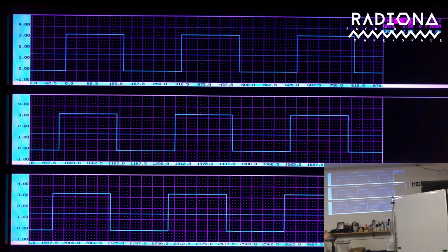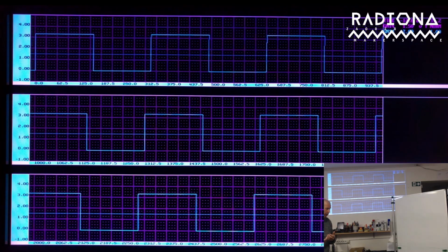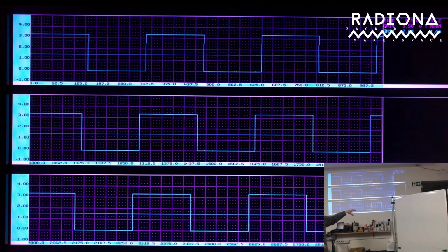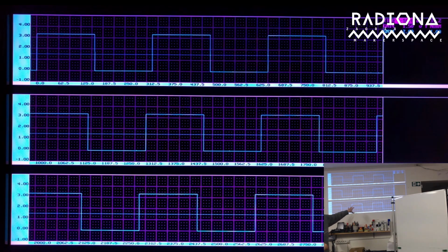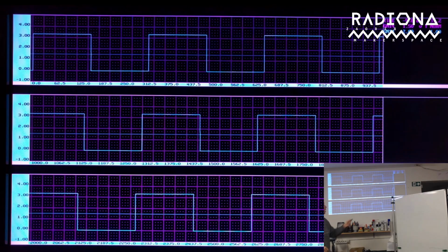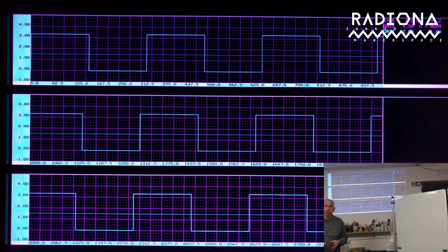So what you are trying to see is sending this data out, maybe then converting that to an analog signal and watching it in an oscilloscope. If they embedded their design with this, they don't need to do that. They capture those data directly and can draw and see what is happening directly in the FPGA. So the library is for debugging your own design inside, not taking the signals out.